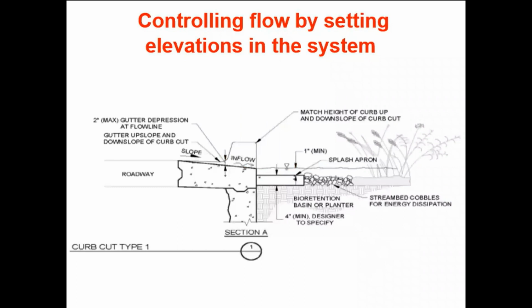And so here we have the same detail in section. Again, water is flowing in, and you'll notice that the splash block is down a little bit. It needs to be down because sediment and such is going to build up there, and that's one of the reasons that we have a little bit of stone back here to also help protect and control the amount of sediment.